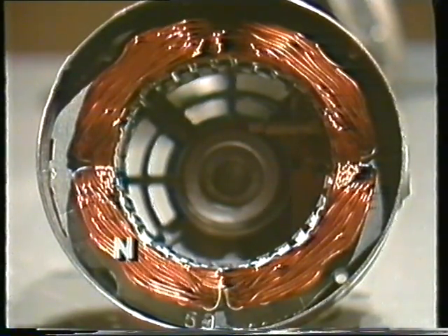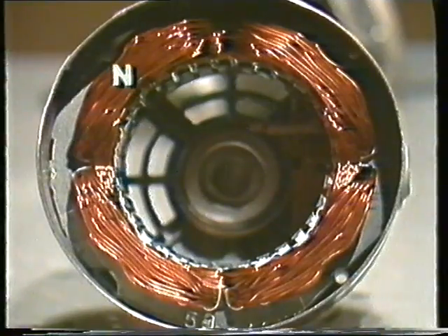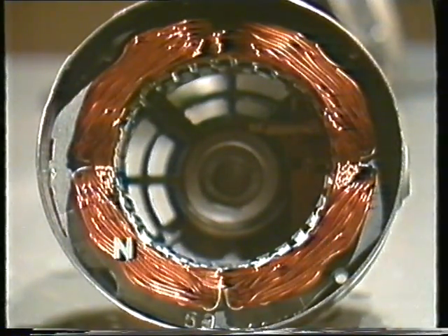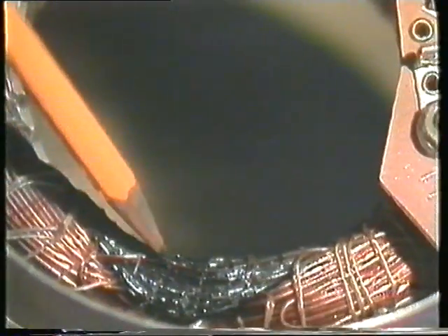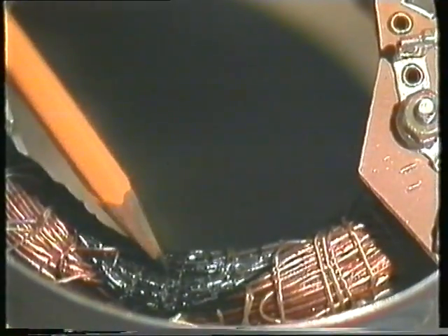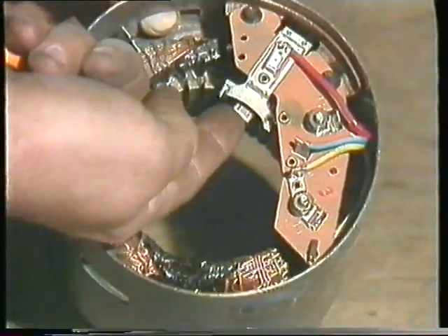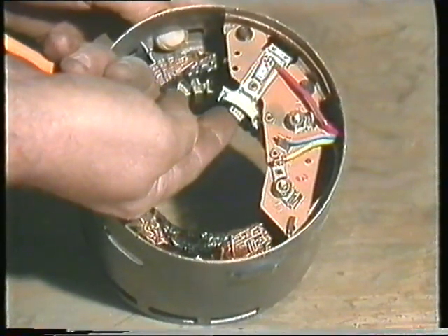Once the motor has come up nearly to full speed, a centrifugal switch cuts out the start winding. It is no longer needed and cannot stay connected because heat generated in its resistance would burn it out. You can recognize a split-phase motor by the two different gauges of wire in its windings and the presence of a centrifugal switch.